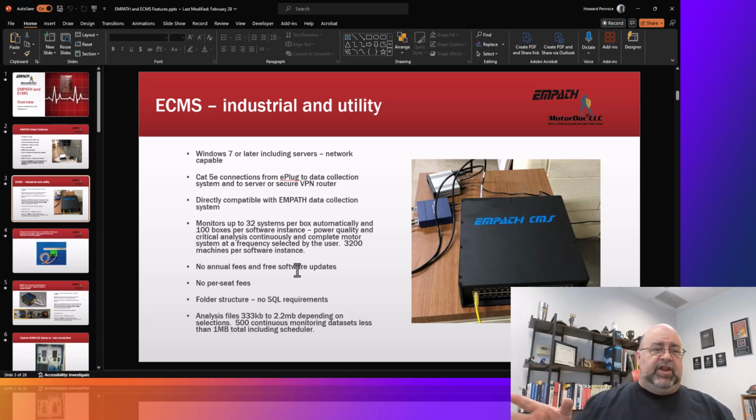One of the cool things about this is the ability, as we talked about before, to see the entire powertrain, incoming power, electrically and mechanically, including bearings, all the components within the motor, including lubrication issues, through a coupling, including the belt. And yes, you can see your driven equipment through a belt, through a coupling, including a flexible coupling, and everything else. I've had people attempt to say that you can't do it, so I went back and I proved it out mathematically as well, because we've been doing it since 1989.